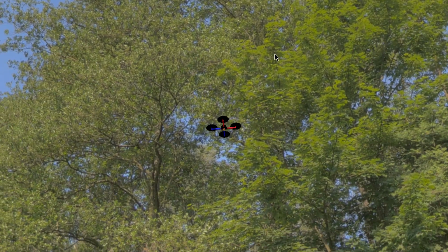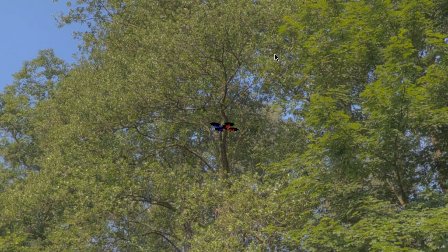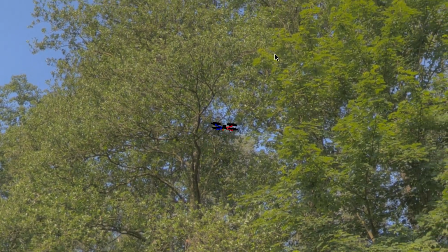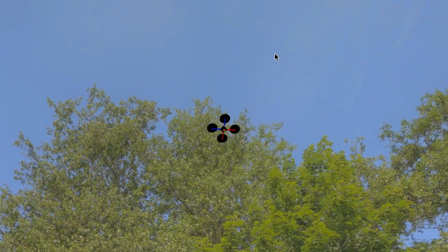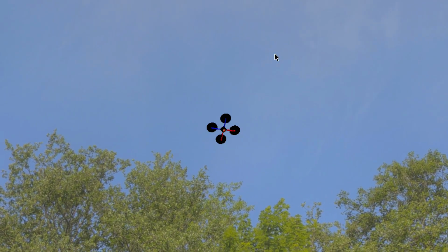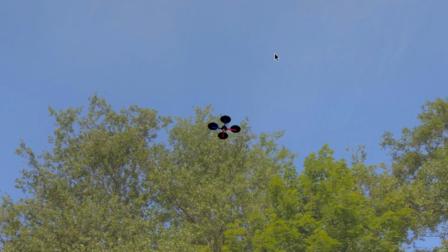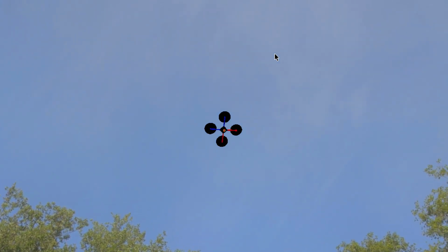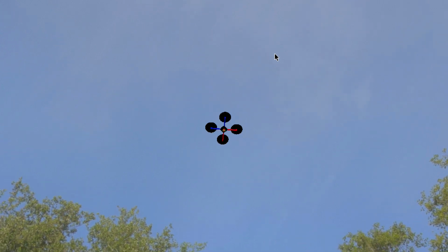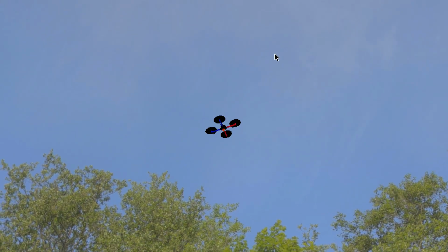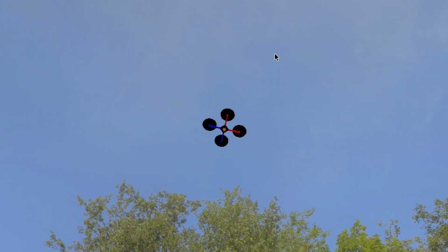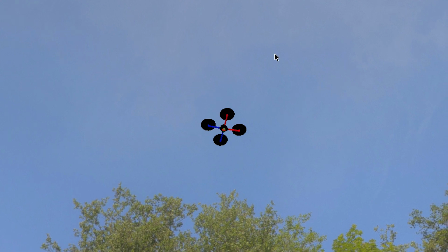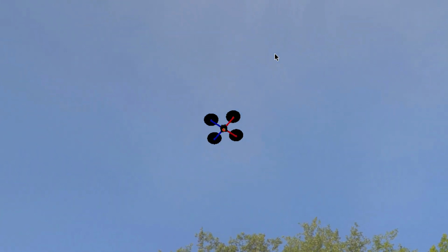For the autopilot system, the team runs a C++ application on the Jetson that constantly sends a stream of positions to the Pixhawk through the MAVLink messaging protocol. The team uses a finite state machine where the drone state space includes the following: completing loop, scanning, flying to position, dropping, and loitering. During scanning, once a vision target is detected, the drone will fly to the calculated position and drop the payload. After the drop is completed, the drone continues with the scanning procedure to find the rest of the vision target coordinates.